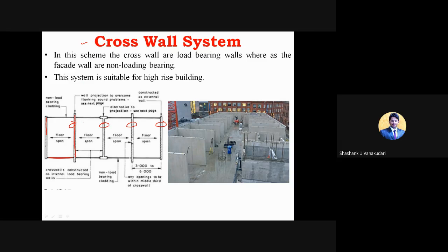Basically these cross wall systems are considered in high rise buildings, because whatever load comes from the slab is directly transferred to these cross walls.